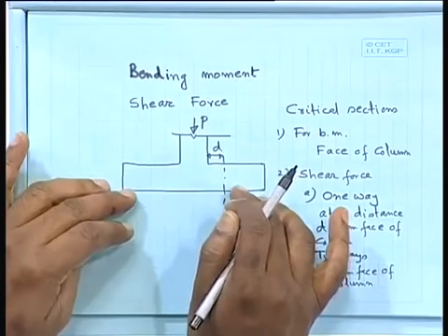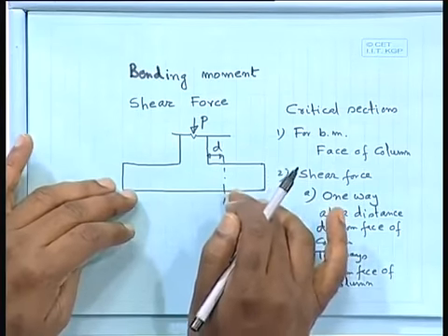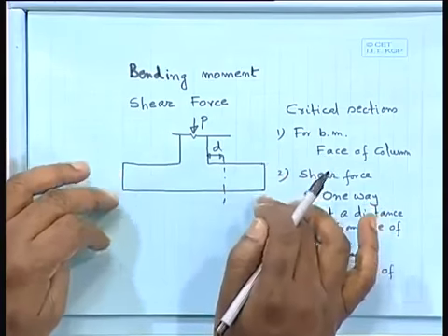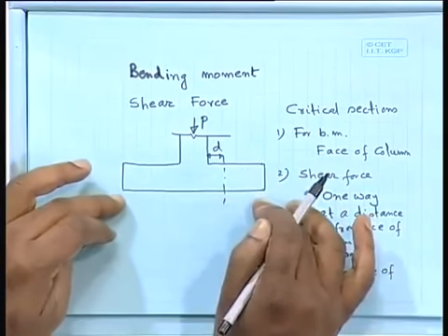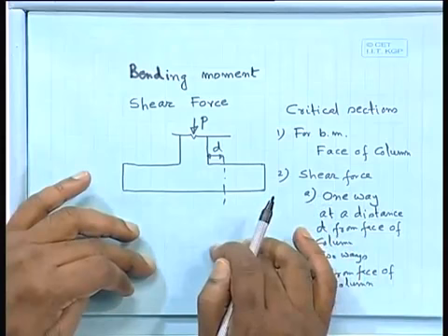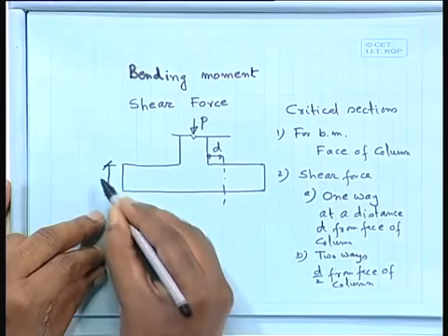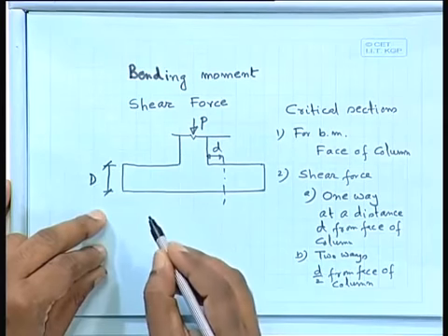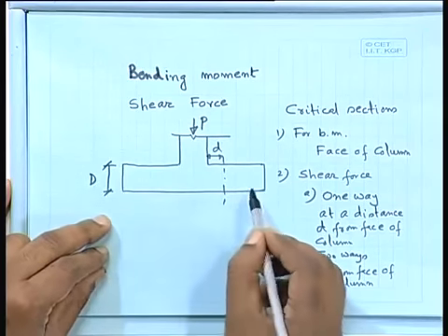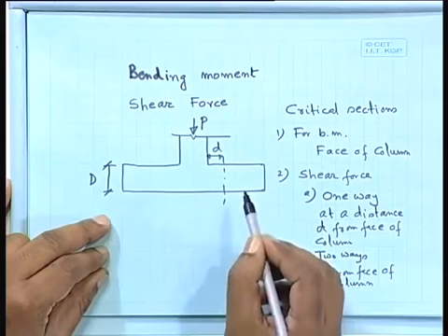Next, you have to provide the section size. You know the area of the footing; it may be rectangular, circular, or square, depending on the situation. Now you have to provide the depth of the footing, the overall depth. 50 millimeter we have to provide as the clear cover, that you should remember.